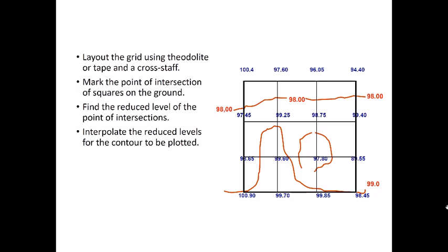So similarly over here, first, when you've done the survey on the ground, you choose a suitable scale for your grid to be drawn on paper or on your software. And once you have that scale, you draw it on your paper, and you mark the values on the specific grid lines. So the grids would be drawn according to scale, but these values would remain as they were in the field. And then you see what's the minimum value, what's the maximum value, then you decide upon the contour interval, then you start drawing the contours from the smallest value.